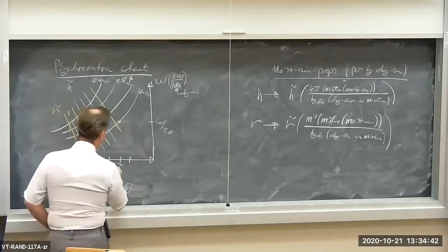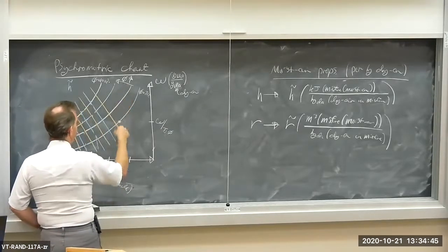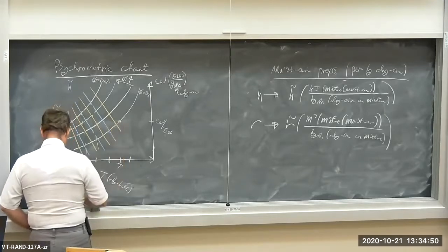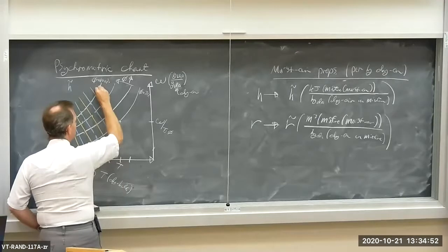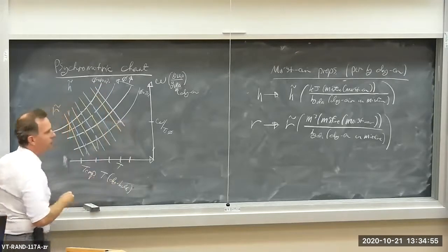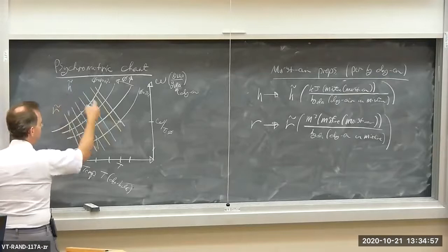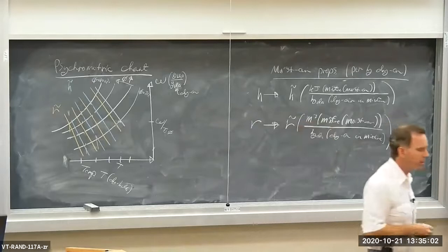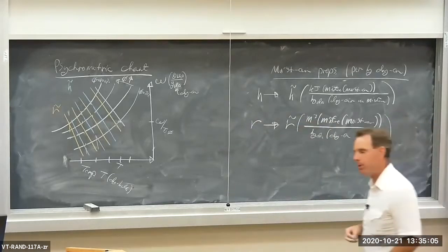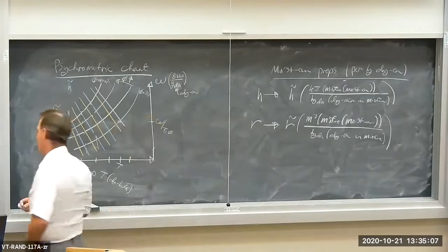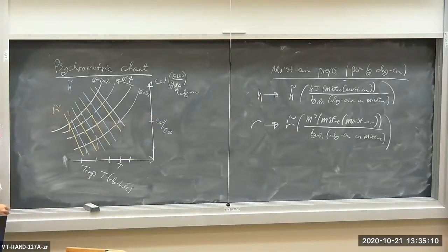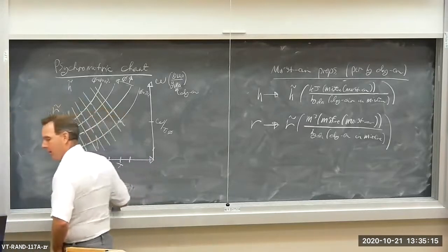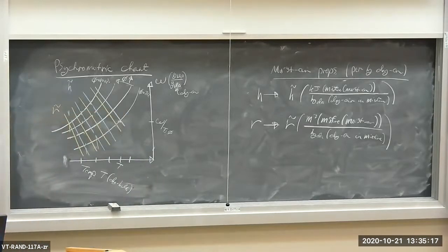So you give me two properties. You give me a temperature and a relative humidity, let's say. I find the state, and then I can immediately go to the nearest or interpolate to the nearest line of constant H tilde, constant V tilde, and I can get my specific volume for the mixture and the enthalpy for the mixture per kilogram of dry air. Okay? So that's kind of how this plot works. There's some other stuff we can do with this plot, but we'll talk about that a little bit later. So let's actually have a look at this thing.